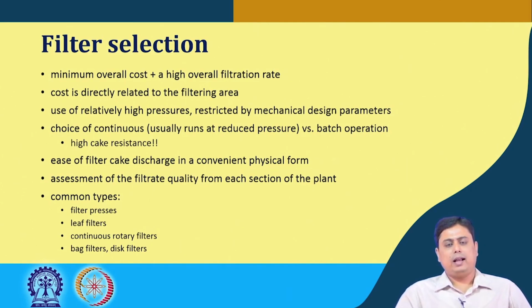The other thing that has to be taken into consideration is the ease of filter cake removal, and that too in its convenient physical form. That is, when the cake is deposited, and if these solid particles are our valuable or desired product, then they have to be easily removed from the filter media.